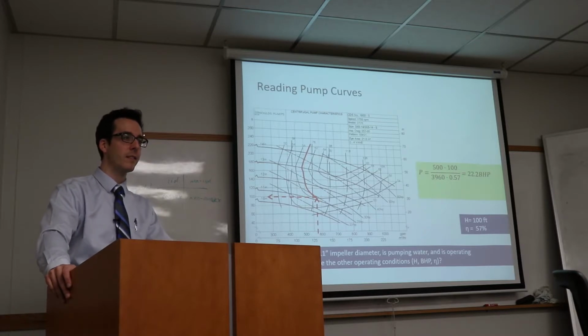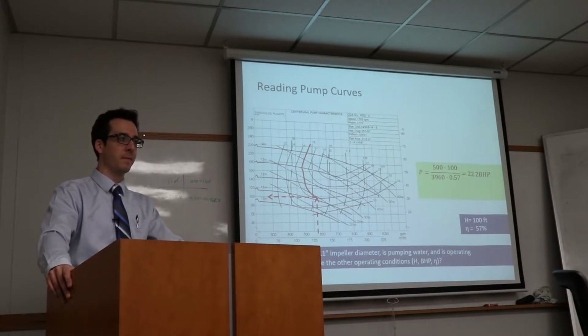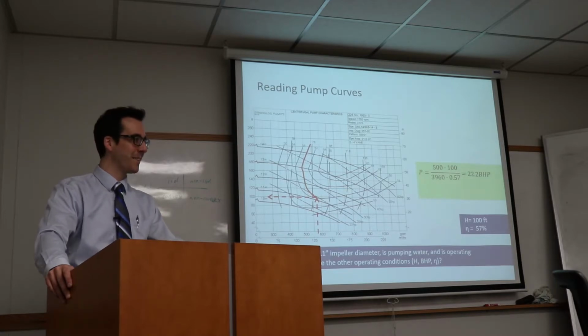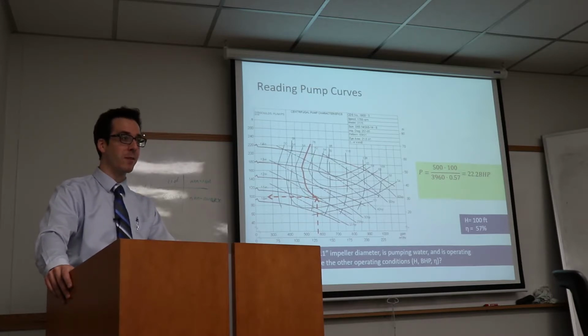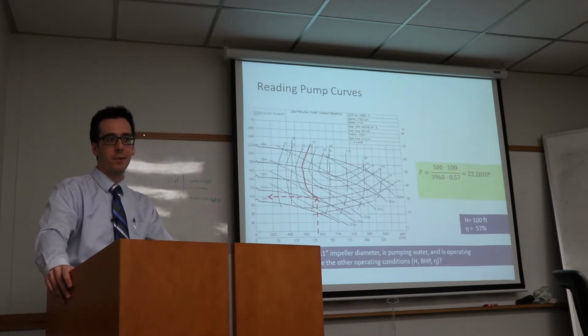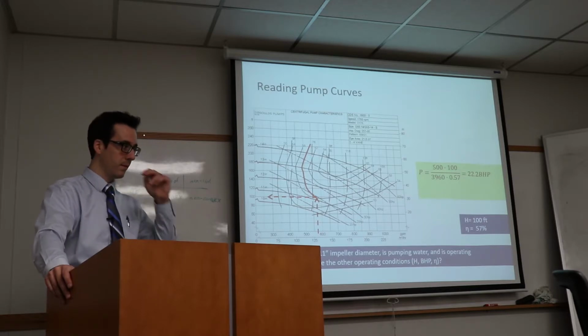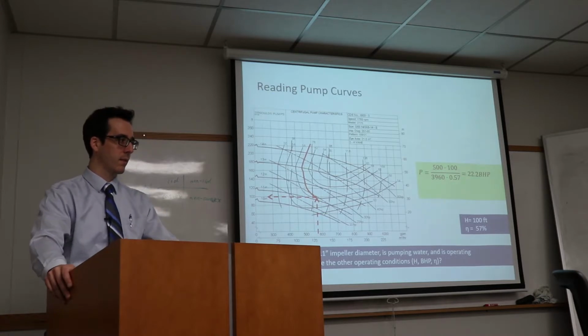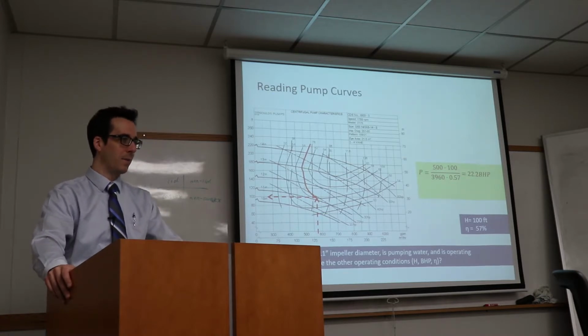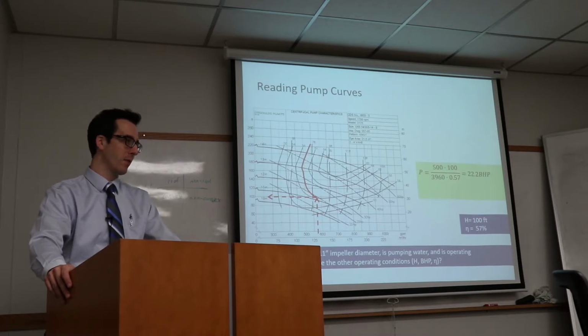Yeah, James? Have you ever seen savings opportunities from replacing a low efficiency pump with a higher efficiency one? Yes, absolutely. Are those economical? It depends, right? That's always a scientific answer. I'm not trying to be ambiguous, but it does. Is it a big pump? Is it a small pump? Are they running it 10 hours a month? Are they running it 500 hours a month? It just depends on how long they use it and what the payback would be. And again, just to clarify, there's one conversation about the pump efficiency, and there's another conversation about the motor efficiency. We're talking pumps here today, but we recognize motors are part of that too.